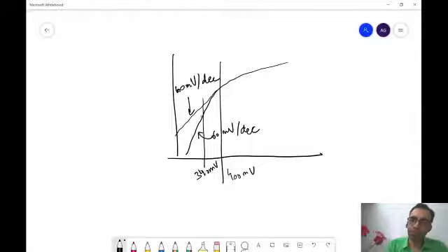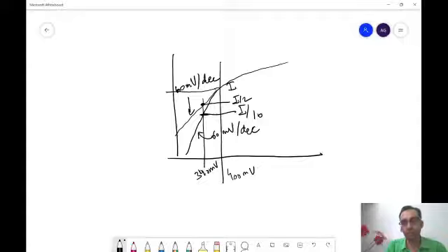What is the leakage for the first curve? If 340 is I, then the leakage over here is I by 10. What about here? Leakage for the other curve? It could be I by 2. You see? So a steep slope means reduced leakage.